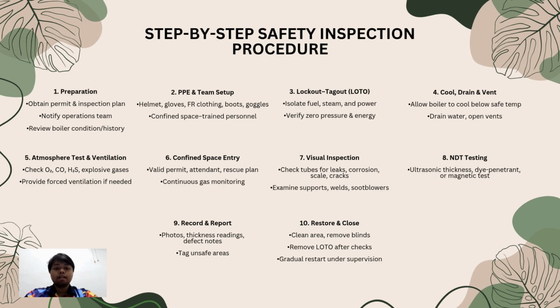Examine supports, walls, and soot blowers. Eighth, NDT testing. Ultrasonic thickness, dye penetrant, or magnetic test. Ninth, record and report. Photos, thickness readings, and defect notes.